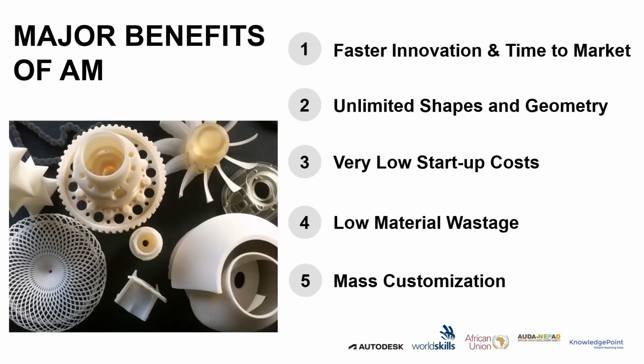Another is low startup cost, which is what we call low investment. It's because it doesn't require tooling, so essentially there is no startup cost. The cost of a 3D printed part depends on the amount of material used, the time it takes the machine to print it, and the post-processing that comes out of it: the removal of the supports, the sanding or priming, the curing, and even the finishing and polishing.